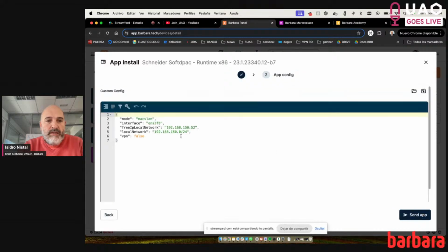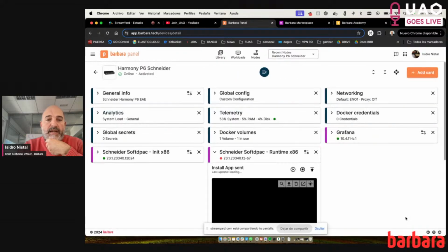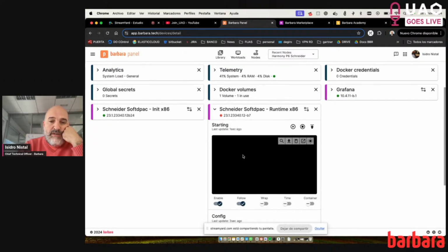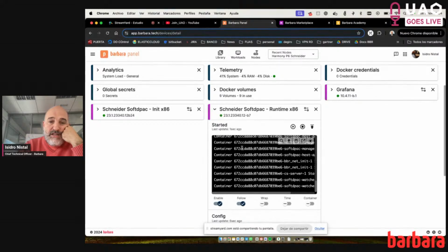Okay, I'm going to click on next. It's asking me about network configuration. So I'm going to put my network configuration that I have in my network card that I showed you before. So I'm going to put something here like an IP that is free in my network. This will be my local network, and I'm going to do it through the VPN. So I'm going to put this as true. So now I have the soft dPAC configured, so I can send the runtime, and it's going to start executing the runtime. Okay. So now, just with these couple of clicks, I have the runtime up and running and ready to be managed through the EAE, okay?